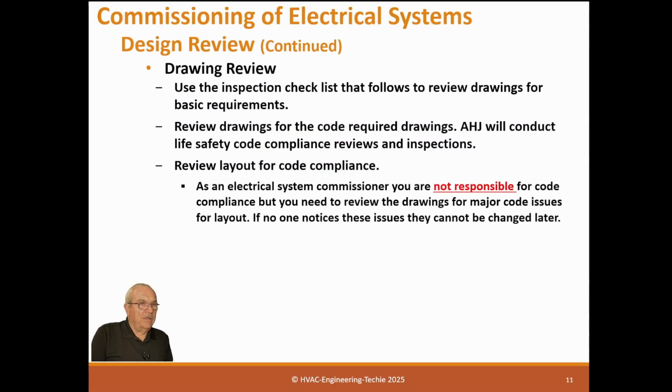Now remember, as an electrical system commission, you are not responsible for code compliance, but you need to review the drawings for major code issues for layout. If no one notices these issues, they cannot be changed later. So it's important. Now, the ones I'm talking about, there's a lot of code items that are important for operators and that helps them actually manage and operate the systems and safely.